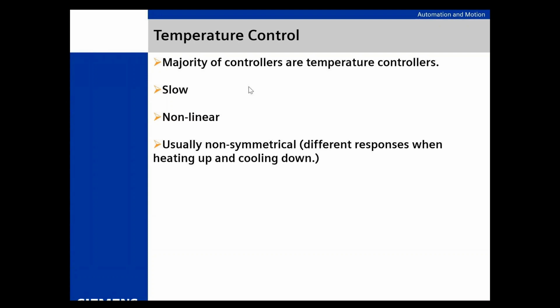Okay? So what you really want to do here is you want to say, what am I trying to do with this control? All I'm trying to do is maintain set point. Is hysteresis a big deal? Not to me too much. I just want to maintain set point. If that's 100 degrees or 500 degrees or whatever it is, that's my main thing. Other than trying to worry about the hysteresis, because a lot of times there's not much I can do about that.